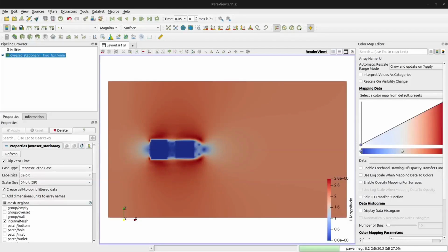Welcome back. In this lecture, we are going to talk about overset mesh. Overset mesh is a technique in which we can have two meshes which belong to different regions overlap, and we solve in two different regions separately. At the boundaries of these regions, we interpolate values. We are solving consistently the same problem in the entire domain. Let's see how this goes on.